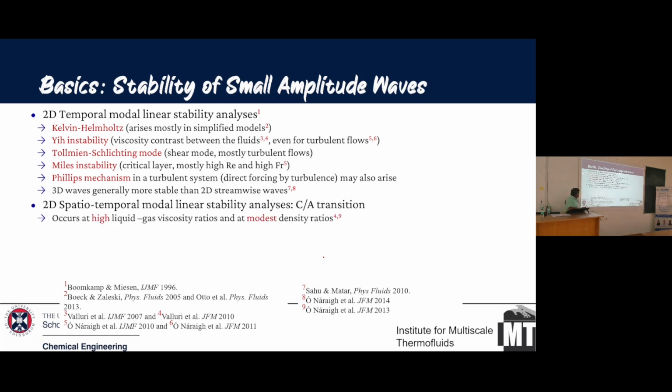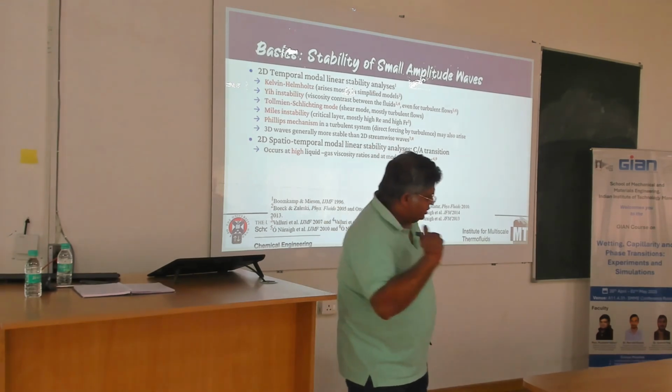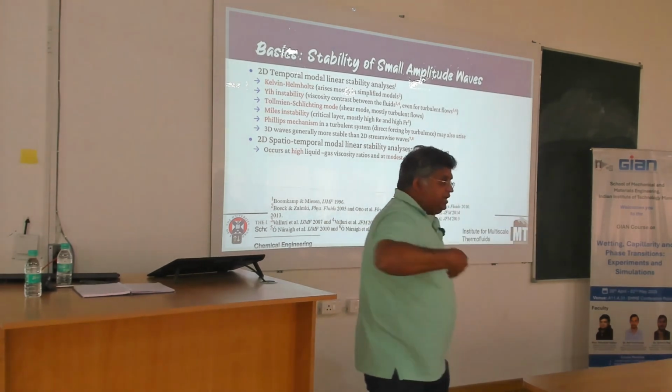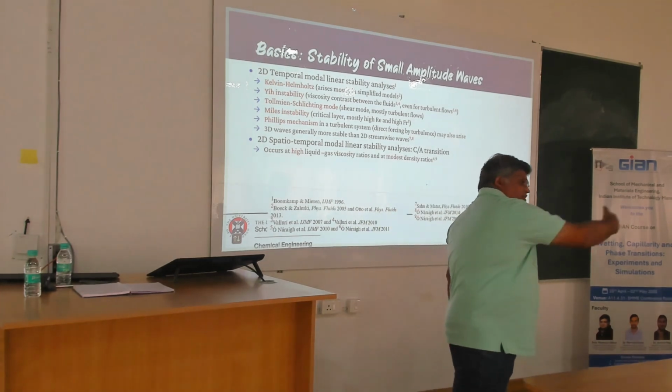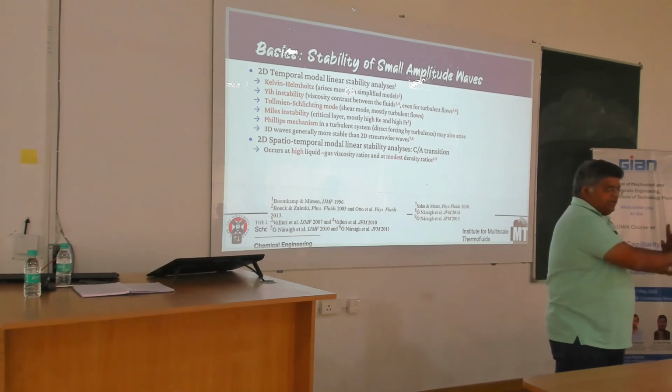So what do we do? One of the things we also look at is how these waves propagate. Now, if I hold a rope towards one side, I can just give a pulse and the wave travels. So the instability is traveling only in one direction. That is a convective instability that is pushed by the flow, if there's a flow.